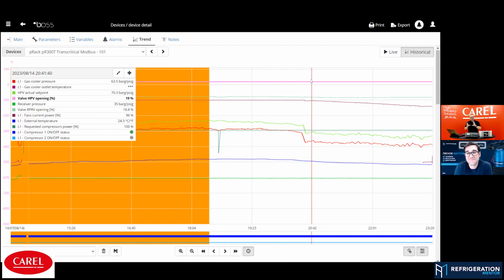On the one hand, if I have enough refrigerant in my application, in my plant, the gas cooler pressure should be higher. And then it's also no issue that my flash gas valve is opening and closing and working. So what could the problem be? I was absolutely clear at this moment there's enough CO2 now in our application, because all of our cabinets and expansion valves are working fine. We receive our temperatures. If we have not enough refrigerant in our application, we would not reach the temperatures.